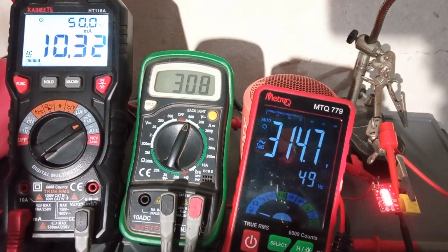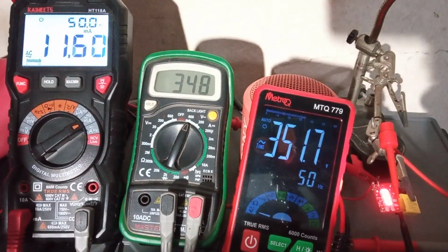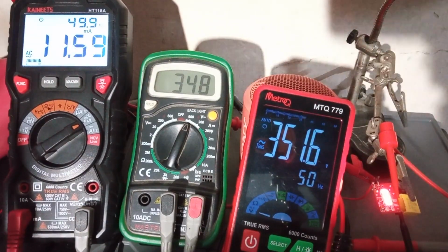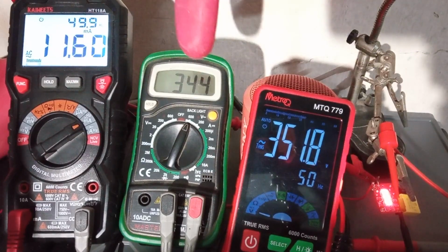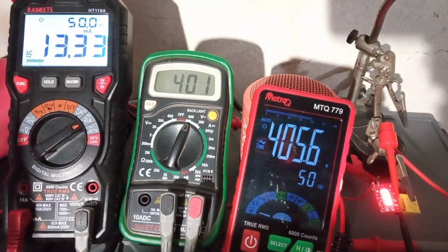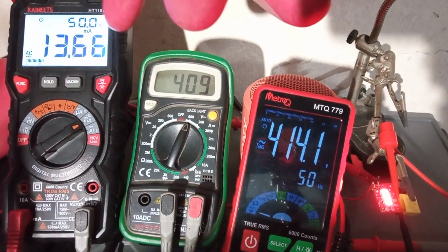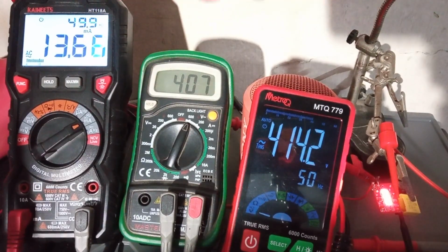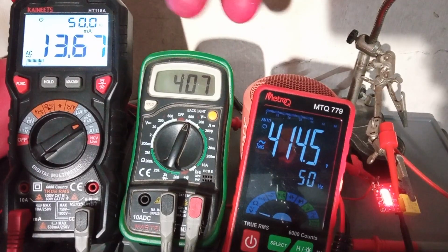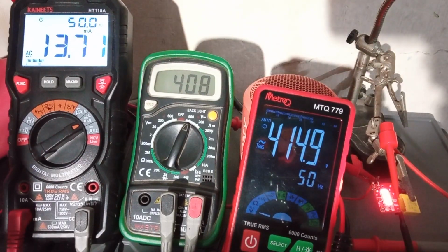If we keep going to, let's say, 350, what happens? So we are around 351 volts. And as you can see, the light glows really nicely. The capacitor is dropping above its limit. If we again keep going to, let's say, 400 volts, we're around 405, something like that. And the whole circuit draws around 13.65 milliamp. And the capacitor is dropping most of the 414 volts, and nothing is happening.